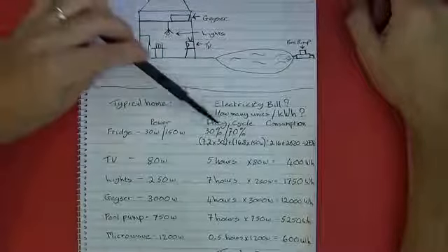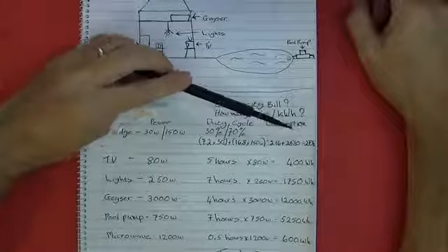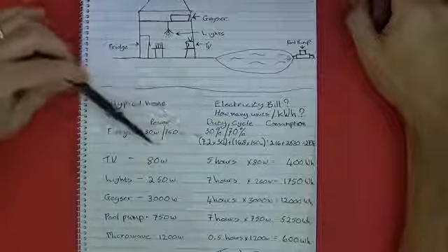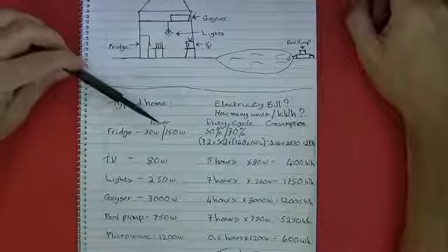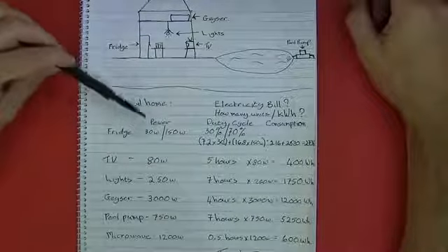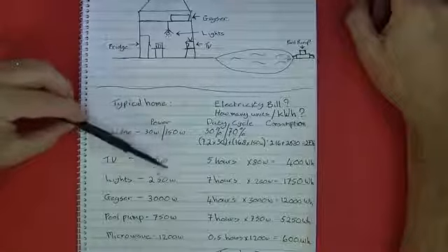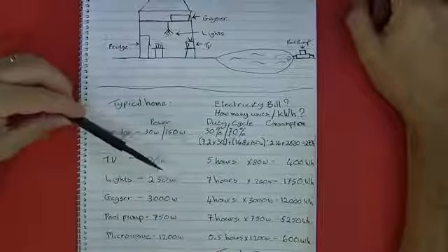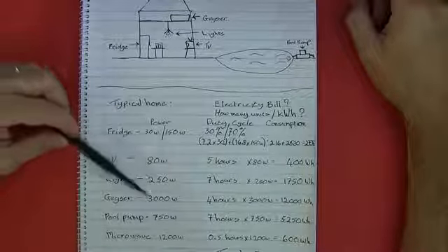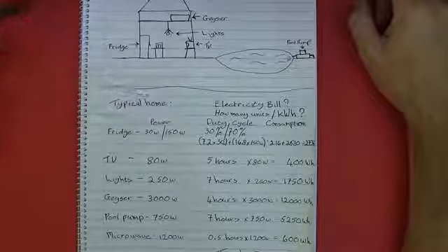So you need to understand that and multiply those figures in order to get a consumption for the day. That is why it's really important to understand these figures, and often even if you read them off the badges of your equipment, you won't exactly know the duty cycle, and often these power figures can be very different in reality. So that's why having measurement equipment to do these audits is very helpful. And I'll show you some of these once we've gone through these calculations.